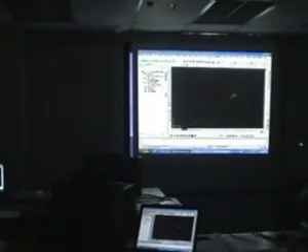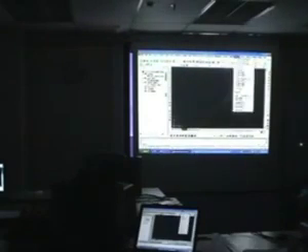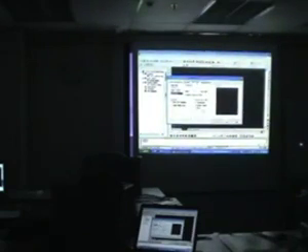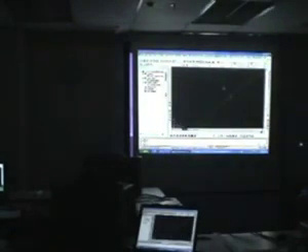The text can also be adjusted. Let's say I don't want so many decimal points, and I want a box around the text. You can go back to the contour style manager. That's under text style. Precision is the number of decimal points, so I'm going to drop this to 0. And maybe I want to draw a border or label around the text. I'll just click OK. It will be updated for me.